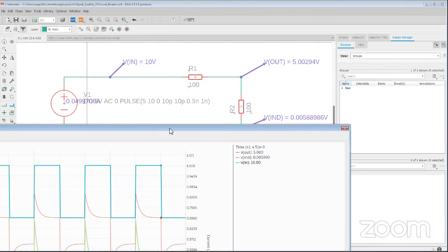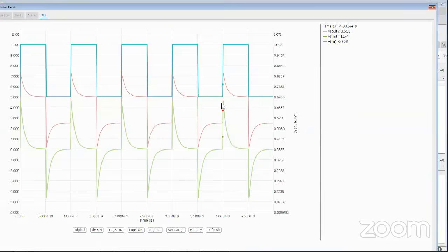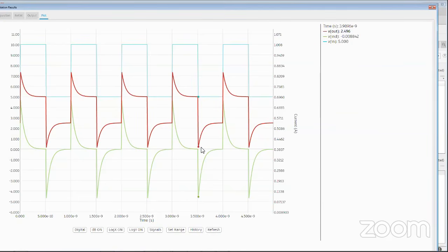Now this is what's known as ground bounce. The key thing to realize here is that it's that voltage change that makes inductance important. If there wasn't this reaction by the inductor to try to maintain the current flow by changing its voltage, then it wouldn't create any problems. You wouldn't have any issues with inductance on PCBs. But because of this action, this reaction from the inductor to try to maintain current the same, you can run into issues like this.